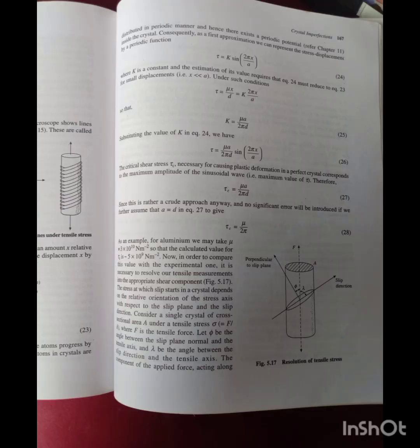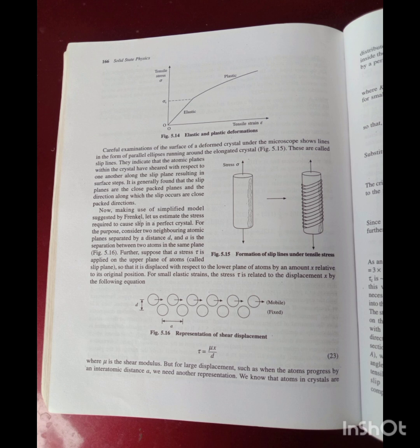and the dislocation motion is due to shear stress. Just onto the right of the dislocation center, an atom is moved further away from its neighbor atom. The atom however simultaneously moves closer to its equilibrium distance from its neighbor atom and releases almost the same amount of energy that has been spent in moving the atom.